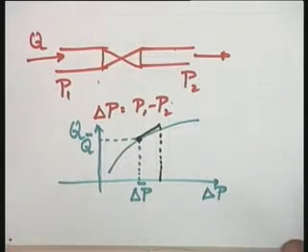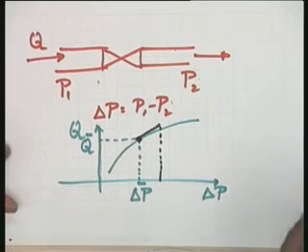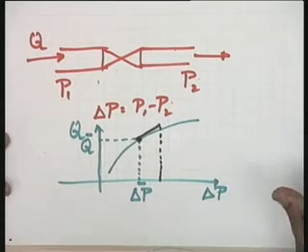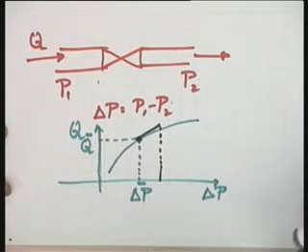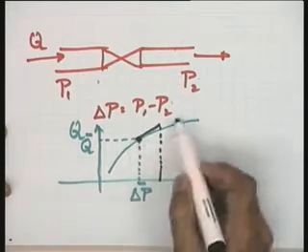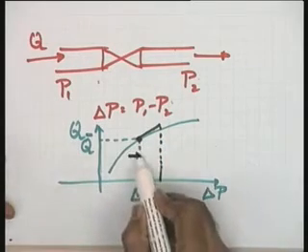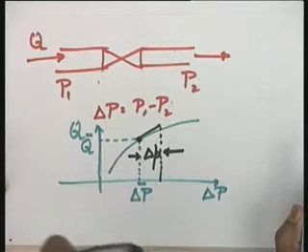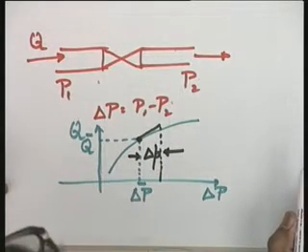But if it is a plant model which is going to be embedded in a feedback control situation, naturally this assumption is quite valid, because we hope we will be able to make a good control system which will not let the deviations grow indefinitely, and hence this assumption will be valid. So, in that particular case, I assume it is a small perturbation, and this small perturbation I say del p. Small p stands for a perturbation variable.